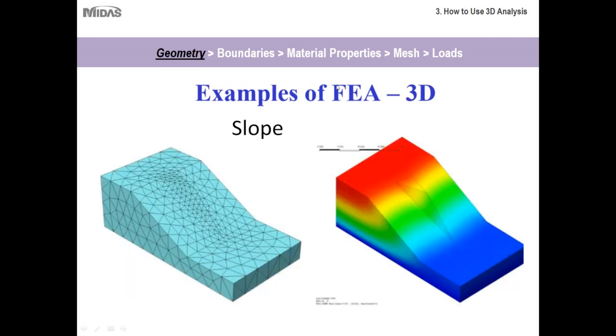And last, a 3D analysis. So this is a 3D slope, and we'll be going over this specific example later. But this is fairly straightforward because of this notch here, this geometry. The engineer opted to model this in 3D. And as you can see, you can only get your results along this plane here, but you can also extrude them along the entire length of the longitudinal direction. So depending on your project geometry and your project type, you'd decide which elements to use.